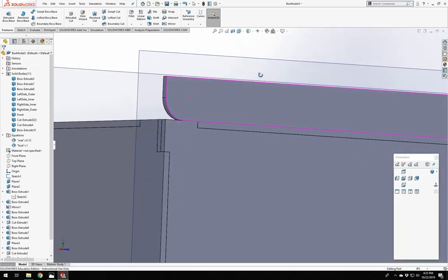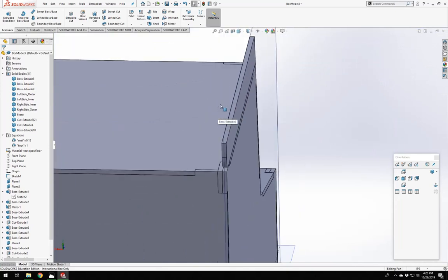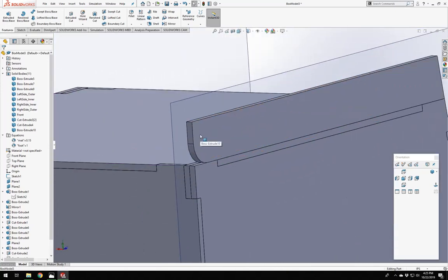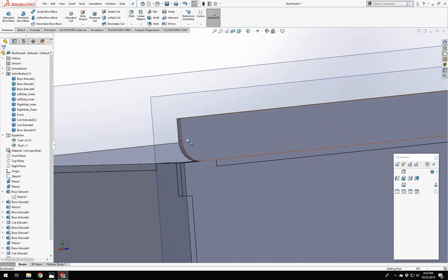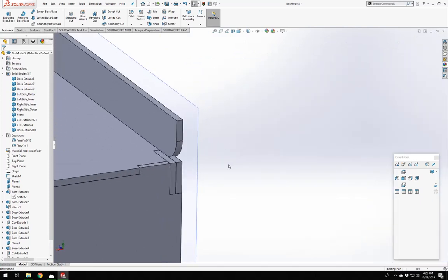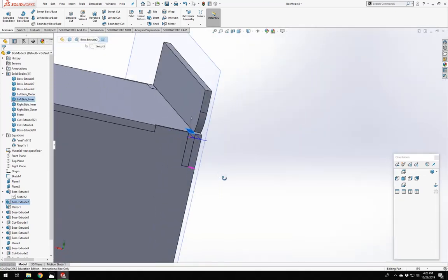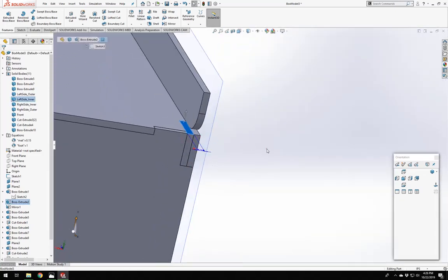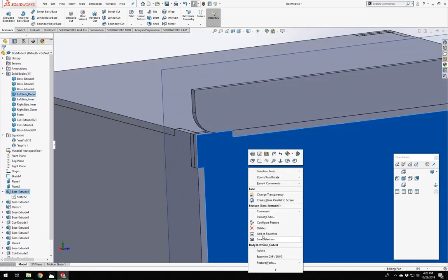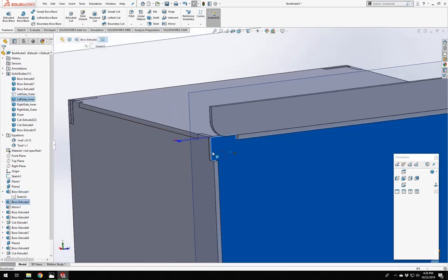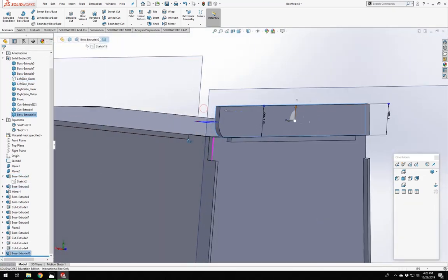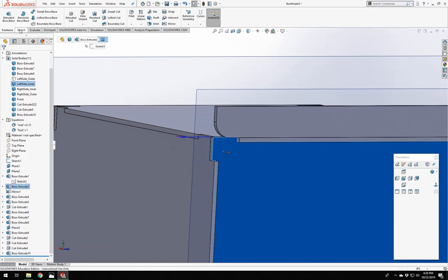All right. This is where things are going to start getting slightly complicated. So we actually need to build this hinge structure into this. And the way we're going to do it is it's actually going to be attached to this second panel of our side. So not the outer one, the second one. So we're going to come into this. We're going to hide our outer one. Hide. We're going to sketch on this surface. We could also sketch on that surface. It will work the same.